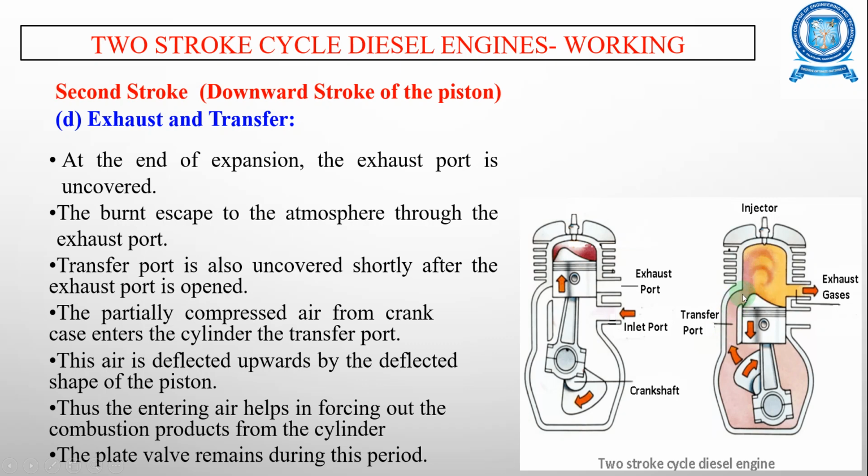The air, while moving from the transfer port towards the cylinder, is deflected by the deflected shape of the piston. The fresh air which enters helps in forcing out the burnt gases to escape to the atmosphere through the exhaust port. Here you can see the inlet port is closed.